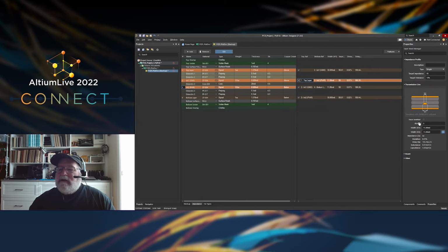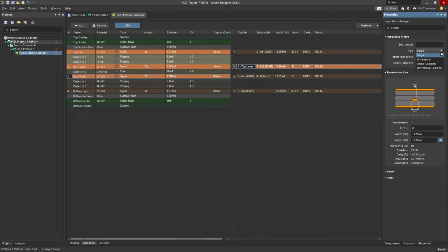Same thing. I can change where the layer is located and which layer the metal is located, depending on the details of the Stackup. So that's how we select and set them up. And again, this is a strip line geometry because I have planes above and below.